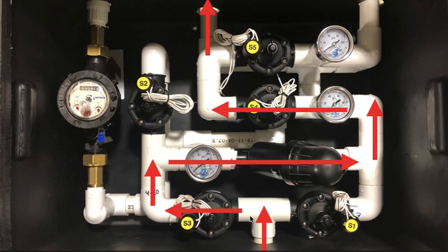And so flow of water, what that looks like, now we're opening up 3 and 4, and so we're reversing the flow of water through this disk filter, and that reversal of water is allowing everything that this disk filter has been catching to actually blast out and leave. So it's going through 3, up and around, reversing through the disk filter, through 4, and then it goes down from here. This is a side out. It goes down to this lower level of plumbing, out to this vent line, and that's going back to the very beginning of the system.